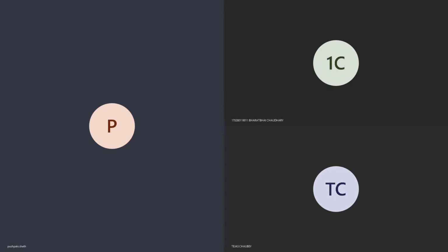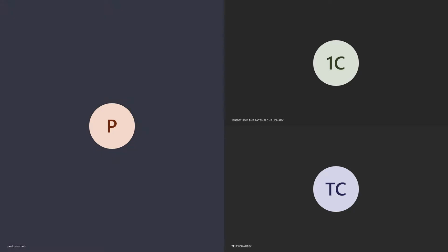If you try to visualize the layout of the thermal power plant, that is the basic aim of today's practical. It consists of four main circuits: the coal and ash circuit, air and flue gas circuit, water and steam circuit, and the cooling water circuit. Right, so these are the four basic circuits of the thermal power plant. I am repeating: coal and ash circuit, air and flue gas circuit, water and steam circuit, and cooling water circuit.